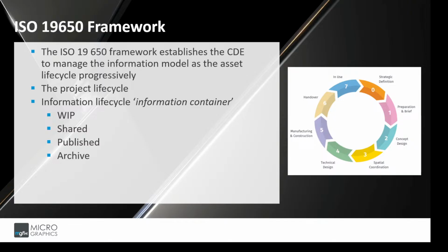Okay, so looking at the ISO 19650 framework, the core purpose of the common data environment as defined by ISO 19650 is to progressively manage the information model across the asset lifecycle from design through operation. And it's important to note that it does not stop at construction, but it carries through to operation. A typical project lifecycle has a variety of stages, but they can be separated into main sections such as the design process, local authority approval, construction, and then building operations.